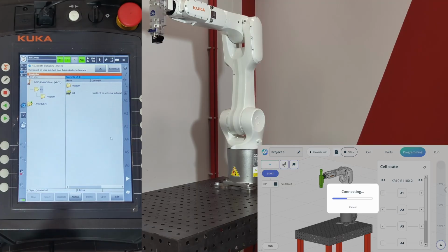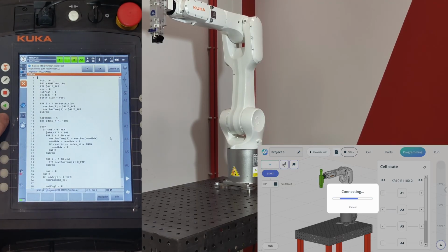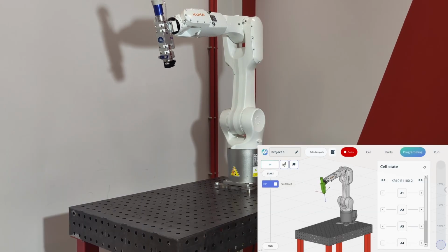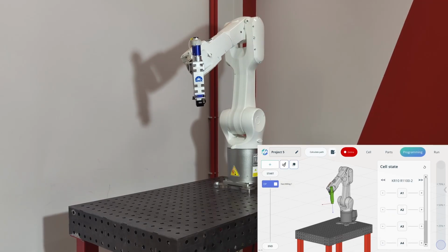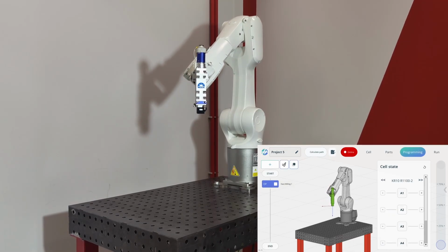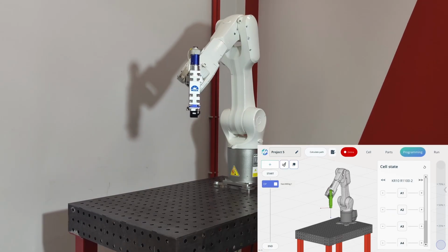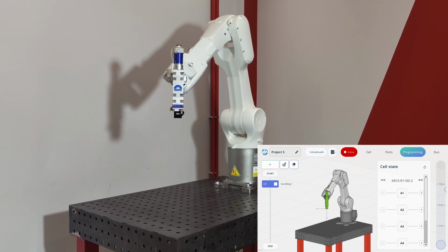Open your project in ENCY Hyper and connect to the robot. If the robot requests confirmation, approve it. This is normal KUKA safety protocol confirming you intend to run programs. Click Next, and the robot will start moving. ENCY Hyper streams commands in real time and tracks motion in real time. You can change operation parameters and immediately run the updated program. The robot follows the path smoothly.